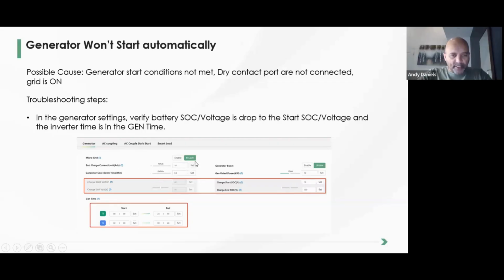So microgrid, what is that? If you enable microgrid, it means the inverter now knows that there's no grid supply, but in fact there's a generator that supplies the site with power. In that case, it will make sure that absolutely no power, not even 1 amp, is exported either via the AC input line or the generator line. Why? Because it's obviously dangerous for a generator.